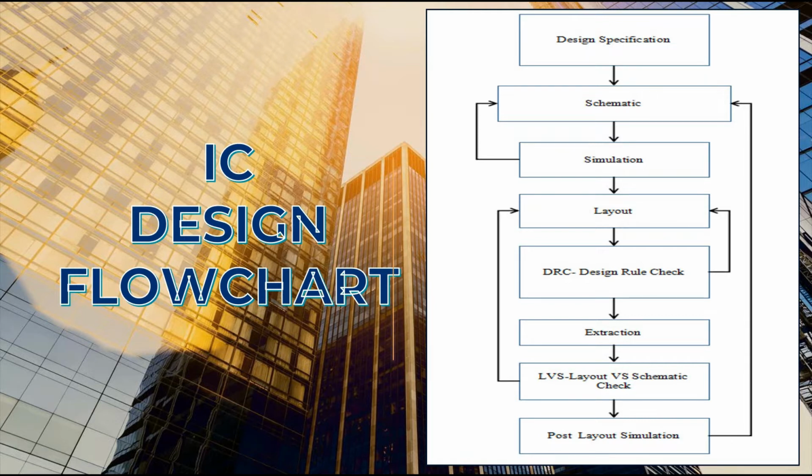And if there is no problem, we're going to the post layout simulation. In this post layout simulation, we will get the output for the propagation delay, which we need to find for both the schematic and also the layout diagram. From the schematic and layout diagram, we need to compare the propagation delay, and then we go back to the schematic, and it's the end of the IC design flowchart.